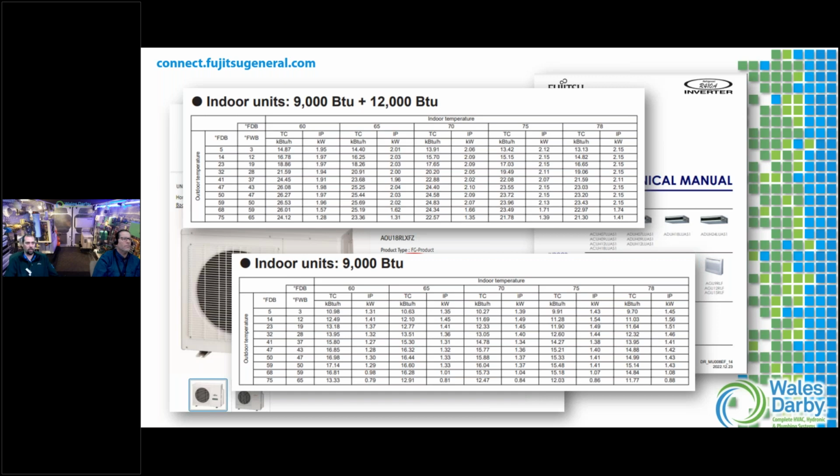These are charts that I think we utilize every day. If you're picking equipment, it's hard to pick a piece of equipment if you don't know what it's going to do performance-wise. Just think about that number there. From a 5-degree outdoor temperature to 70 indoor, it's a 65-degree spread. Now you do the cooling side, 95 to let's say 75. You see how the load really is in ratio to the difference in temperatures. Oh yeah.